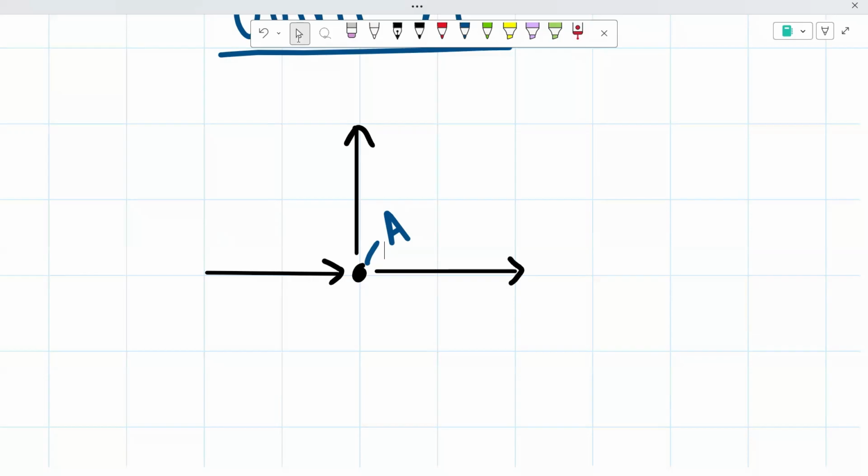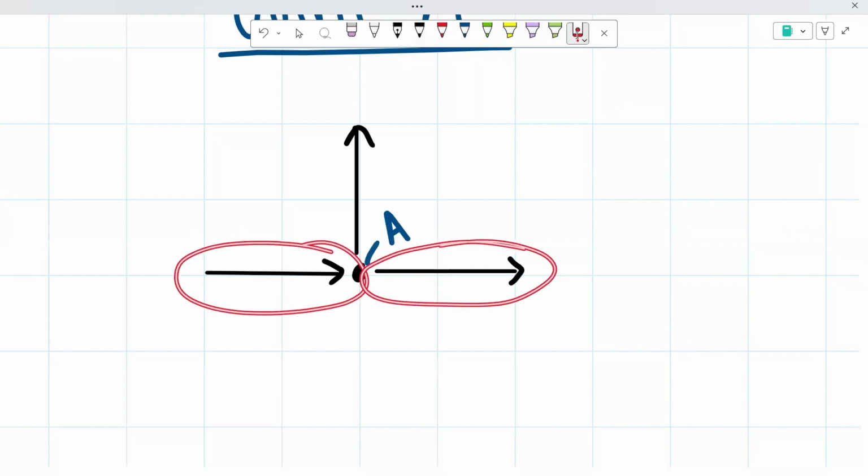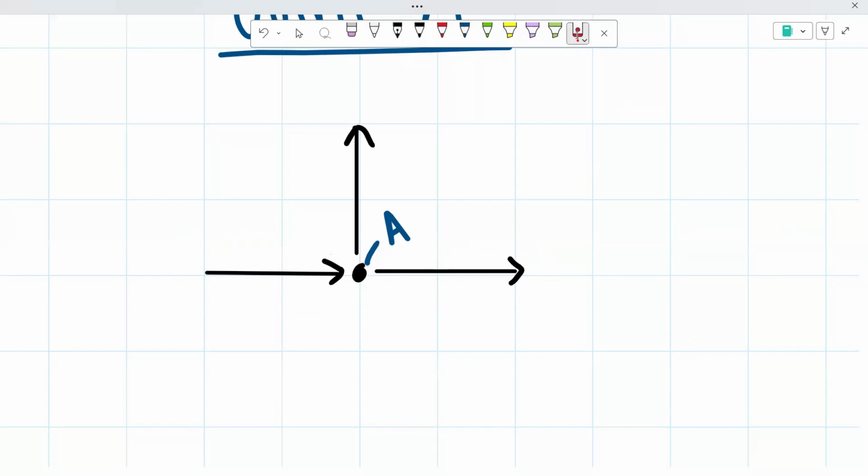And as you guys could see, this joint falls underneath case 2, which is sometimes referred to as the windshield wiper case, because there are three members at this joint. 1, 2, 3. Remember, to satisfy case 2, it has to be three members, no more, no less. So we have three members that meet at a joint. Two of them are collinear, which would be our reaction and our member AB.